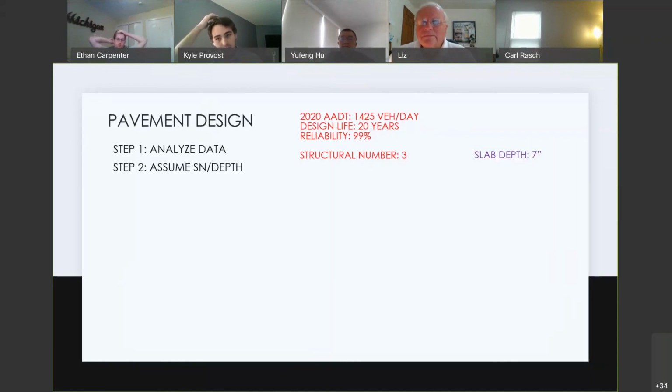Our team designed a typical MDOT trapezoidal ditch with a 6-foot bottom and 1-on-4 side slopes. As seen in the vertical curve section, there is a 5% slope running down to the river. MDOT recommends that the max fill height of our ditch is at least 1.5 feet below the shoulder, so we use the fill height of 2.5 feet to determine our max velocity and flow. Utilizing these equations, we determined a max velocity of 17.44 feet per second and peak discharge rate of 697 cubic feet per second.